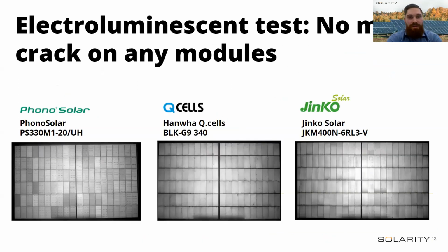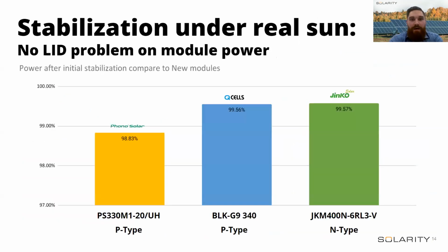So there are results of that electroluminescence test. We couldn't see any micro cracks in these modules. Cells are in good shape. So, stabilization under real sun. We couldn't see any LID problem.